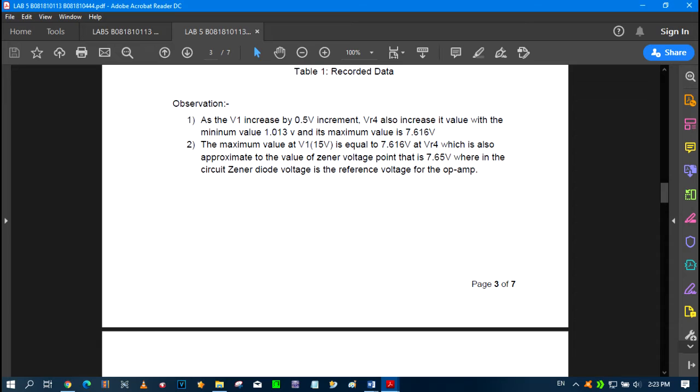R1 and R3 are the voltage divider network used to sense any change at the output. The change sent by the divider network is sent to the inverting input of the comparator, while the reference voltage held by the Zener diode at the non-inverting input of the op-amp is applied to the base of the transistor that acts as a gate. If the output voltage decreases, the increased base emitter voltage causes transistor Q1 to conduct more, thereby raising the output voltage, maintaining the output constant.